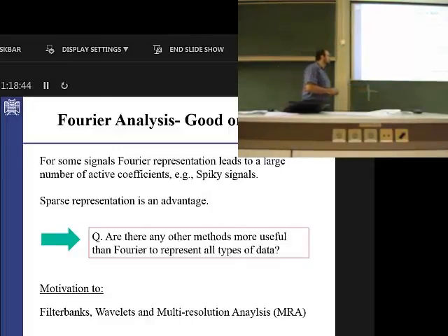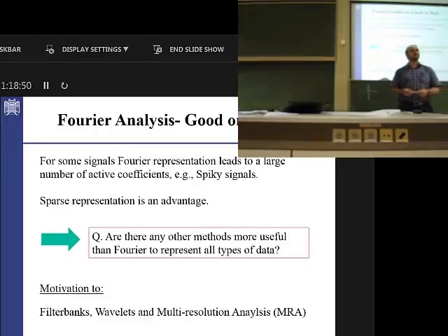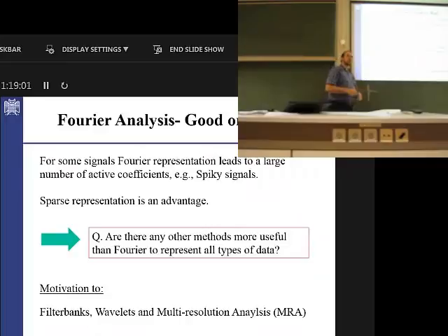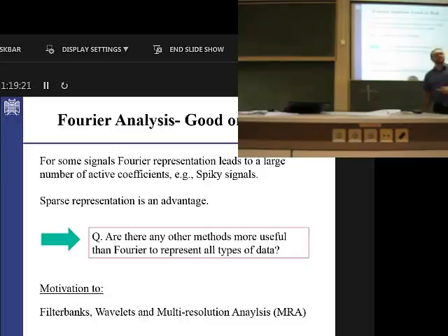And there is another difference I mentioned here. We will not find time to say that, and that's the point of question: if they are the same, why do we have these two different subjects in the same lecture? Let's give the answer at the moment. Filters are in the frequency domain. So when we are dividing the spectrum into different slices, just remember these are important statements I'm telling you. And maybe it's a point of question for many students, even though they know what a filter bank is and what a wavelet is, they don't know why they should use one with respect to the other.